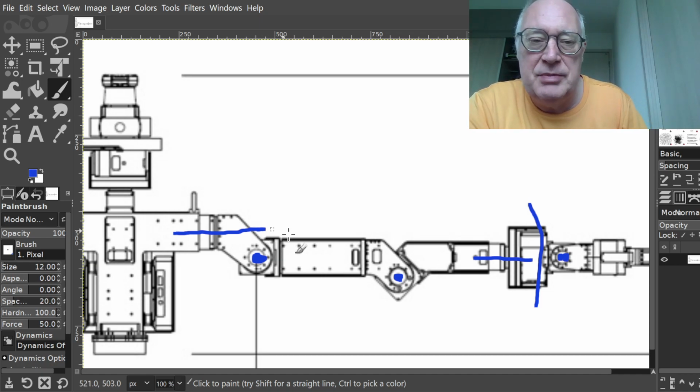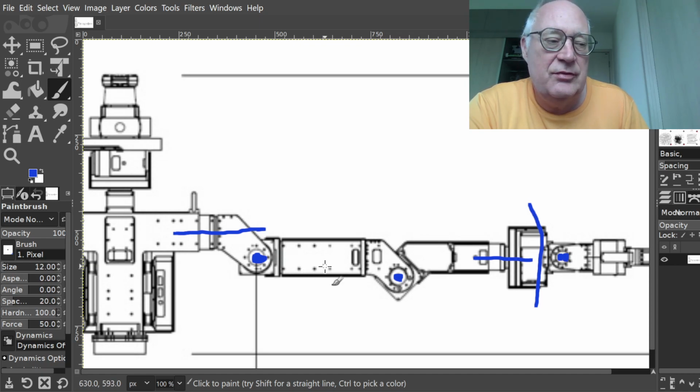You of course can compensate for that in software, but the less surprises you build into your kinematics, because it's hard enough to think about 3D for humans, the less catastrophic failures you're gonna have with your robot. So here, for this particular joint, the horn is on the outside, is at this location, so I want Z pointing out for this point.